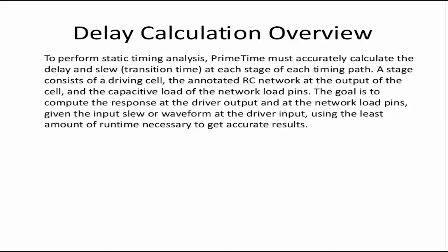So what is the goal? The goal is to compute the response at the driver output and at the network load pins, given the input slew. Input transition is a requirement for PrimeTime to calculate the output delay plus the output transition. Let's see a figure which will explain it all.